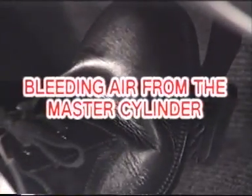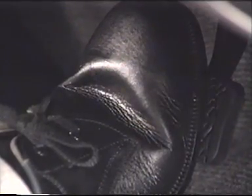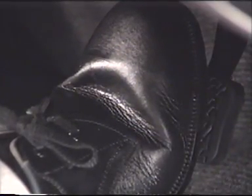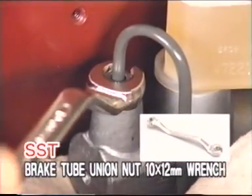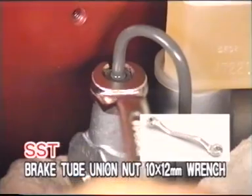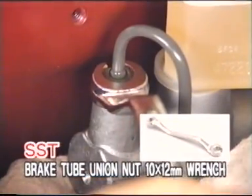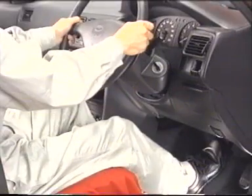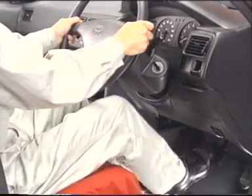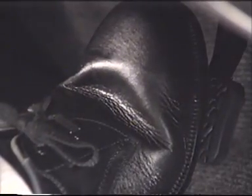First, bleed air from the master cylinder. Confirm that there is adequate fluid in the reservoir tank. Loosen the brake tube flared nut using the SST. Slowly depress the brake pedal and hold it down. Be sure to operate the pedal slowly. Rapid operation would break the air into smaller bubbles, making it very difficult to remove.